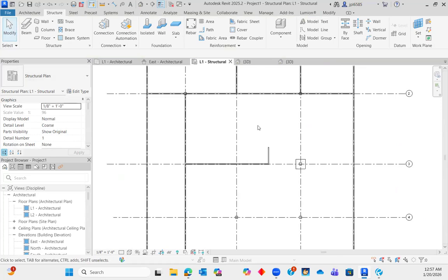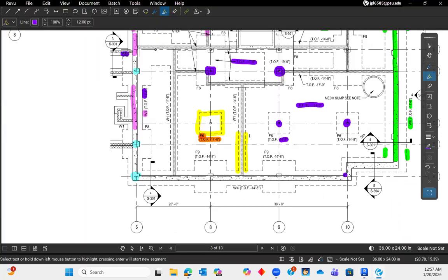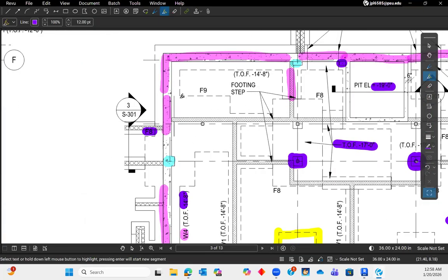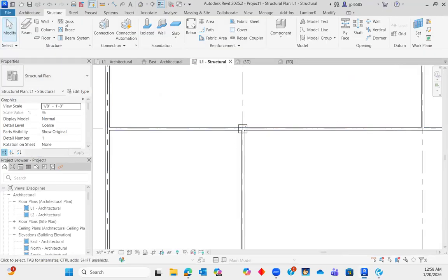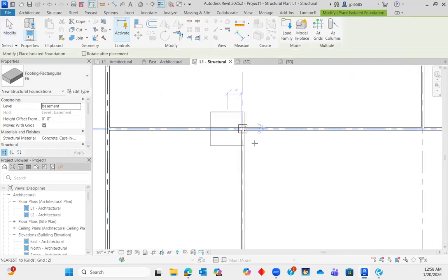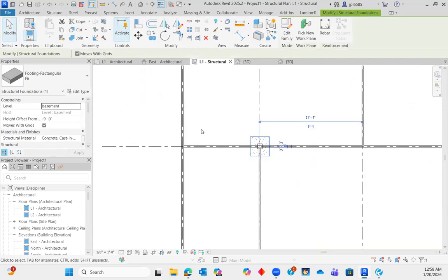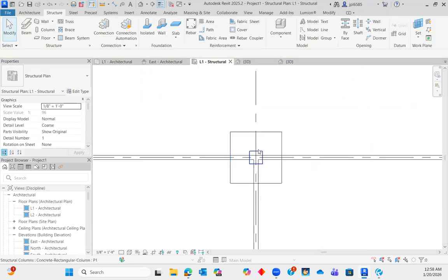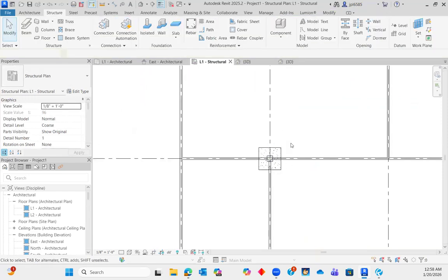Like I said, make all of your footings first. Then I'm going to show you an example like this where they all run into each other. I'm going to make a new footing. Actually, no, it's fine, I'm just going to use this one. It's not at the correct spot because this pier is not at the correct spot, so I'm going to put it -8 inches down. Apply. Click OK. All right, cool.